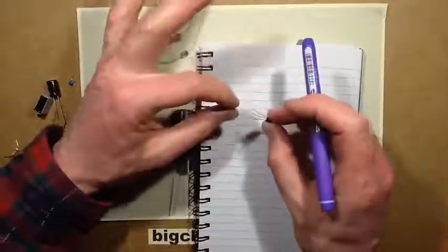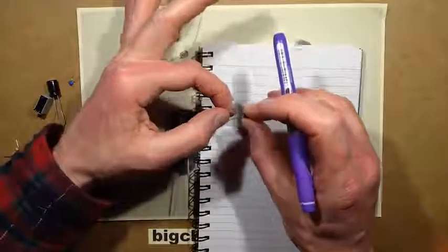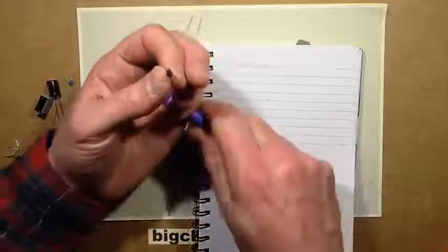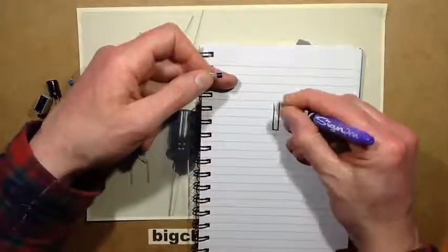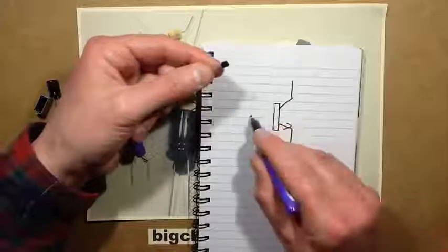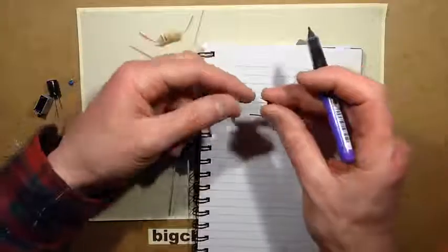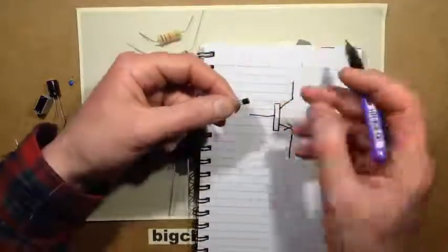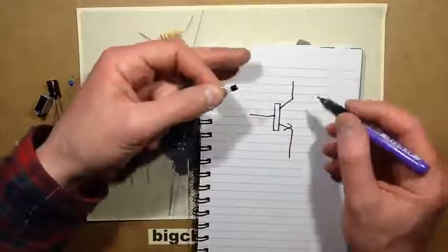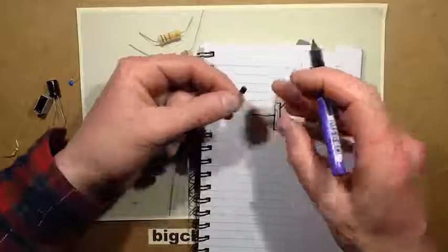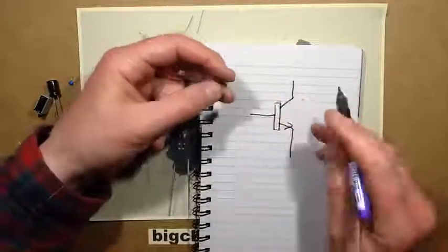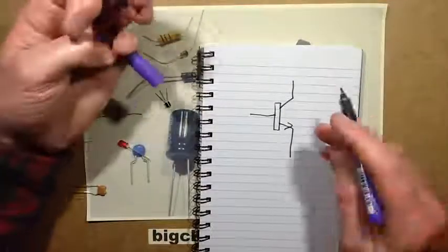And for simplicity, I'm just going to show the basic NPN silicon transistor, one of the oldest fashioned types of transistors about. And the symbol for it is this. You get 3 pins, and if you ever want to find out what the pinout for your transistor is, if you're not 100% sure, just go on Google and type its number in, like 2N3904. Google it, look for images, and you'll find pictures of the transistor with the actual pin designations printed under them. It just makes it very easy to find data like that.